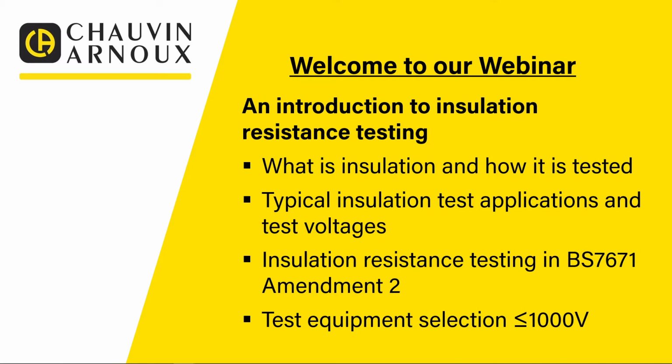We're going to start off with what is insulation resistance and how is it tested. We're going to look at some typical applications and test voltages. We're going to have a look at the insulation resistance testing requirements of BS 7671 Amendment 2, the new standard that's come out earlier this year in the UK. And we're going to have a look at selecting insulation resistance test equipment. For this session, as I said, we're going to concentrate on voltages of 1000 volts and below. So the 5 kV, 10 kV, 15 kV testers we'll focus on in the next session. In this one, we're really looking at the low voltage type applications.